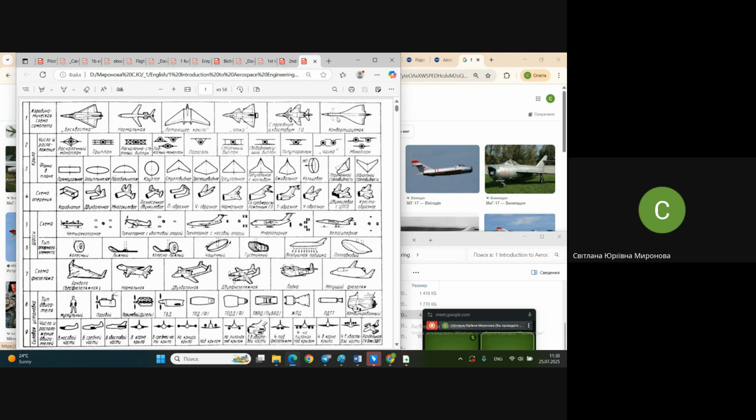Convertible means the stabilizer appears and disappears during the flight. You may move it out and you may hide it. By the way, the airplanes I mentioned yesterday, two airplanes, the European Concorde and the Soviet supersonic airplane Tupolev 144, have a convertible aerodynamical scheme with a stabilizer, which is a canard actually, but it's hidden during the supersonic flight.